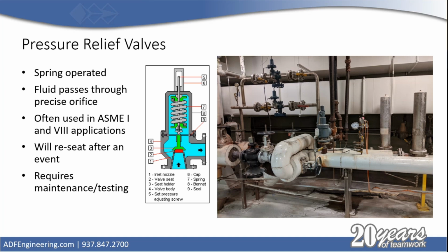One important distinction about relief valves is that a lot of people are looking for sizes that match the pipe they're on, or maybe don't understand how they're sized, but the governing criteria for a relief valve is the orifice diameter inside. And there are very specific orifice sizes that are published by ASME and API that govern the various orifice sizes, and those directly correlate to relieving capacities.